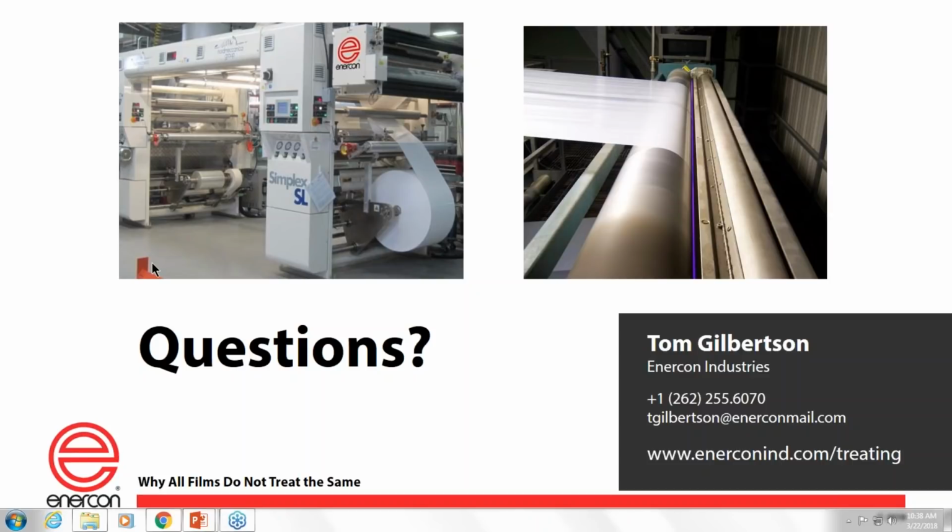That's fine for that purpose. But if you're really trying to tighten down your dyne testing, a dyne pen is not the right tool. The tool to be using there is actual dyne solutions and a Meyer rod. So you take a number 4 Meyer rod or number 6 Meyer rod and use dyne solutions. And there's a test method out there for this. Mark, refresh me on this, but I think it was a TAPPI test method with the Meyer rod. Is that with the ASTM?